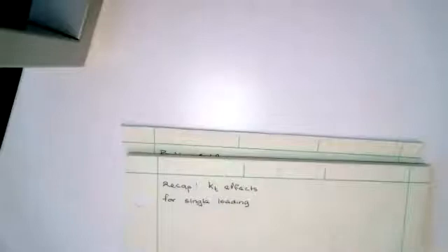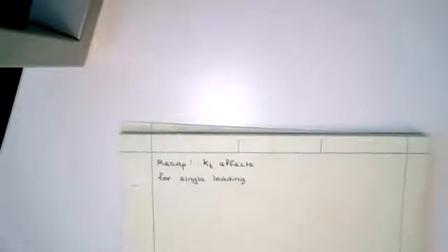Now, KT is extremely important for repeated loading, and that's what you're going to have to deal with most in mechanical engineering fatigue. Okay. And the book makes light of KT for single loading, and you need to be careful.